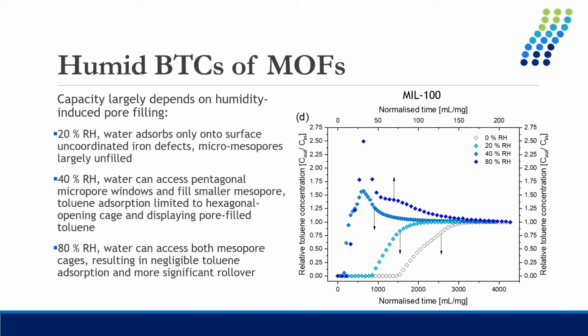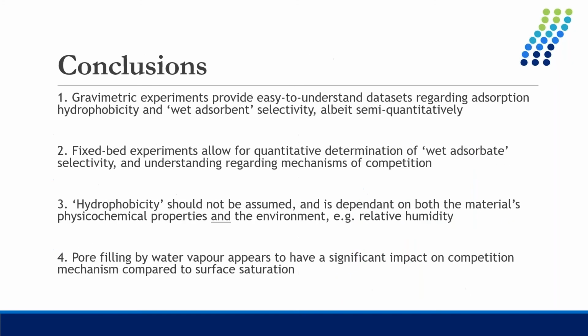It basically showed us that our hypothesis regarding the adsorption mechanism was correct, and that pore filling is an essential adsorption phenomenon. So, conclusions. Gravimetric experiments, so experiments using DVS, can provide really useful information regarding hydrophobicity. It's easy to understand, especially when calculating these hydrophobicity indexes I mentioned earlier. And we can also generate wet adsorbent selectivity, albeit semi-quantitatively regarding the mechanism.